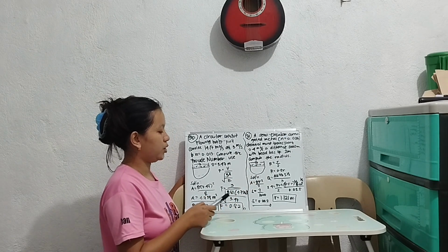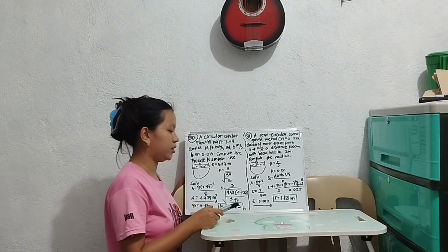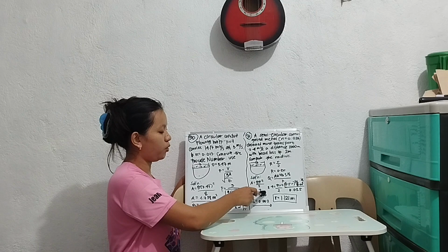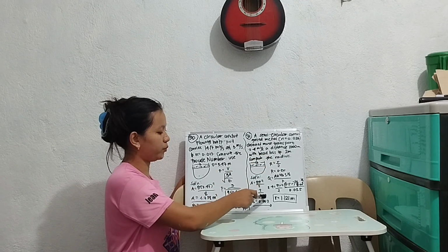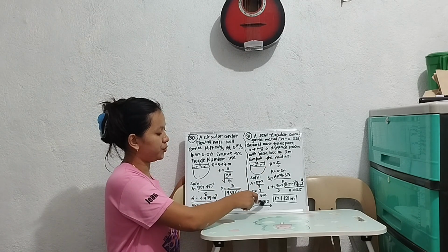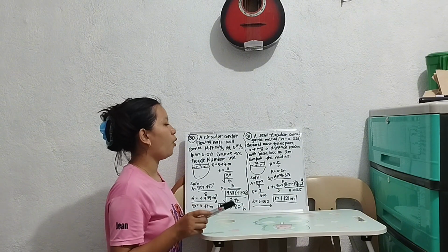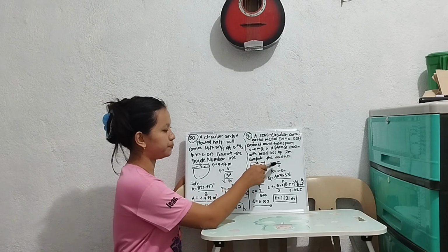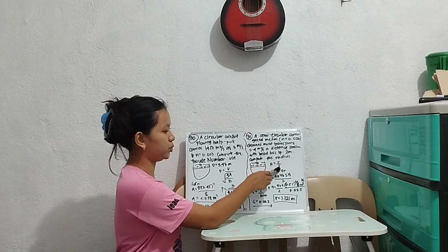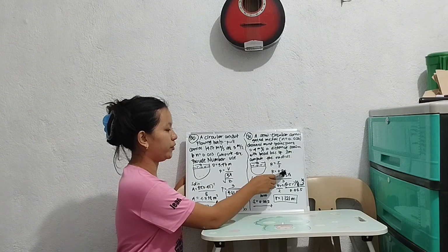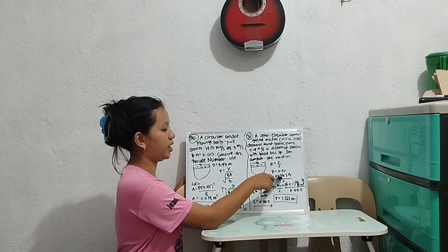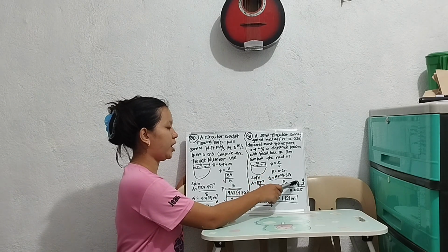So first we need to find the S, or the slope, which is S equal to head loss, 2, over length, which is 1,000. So 2 over 1,000. The answer will be S is equal to 0.002. So the question is we need to compute the radius. We have the hydraulic radius equals radius over 2, so R equals 0.5 R. Then we have the formula Q is equal to area times the hydraulic radius raised to the power of 2/3 times the slope raised to 1/2, over N.